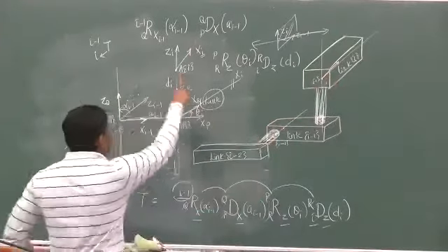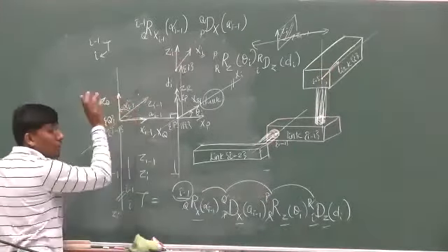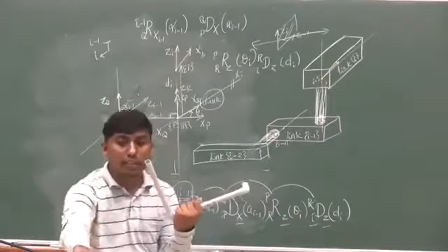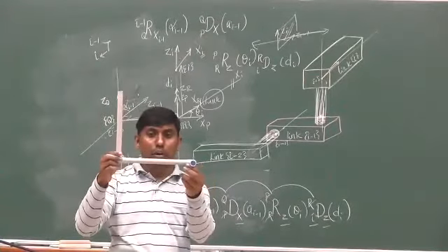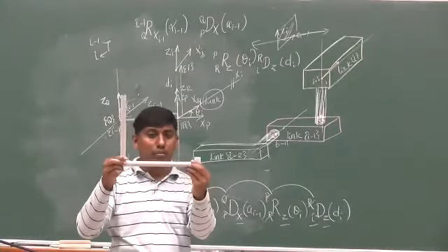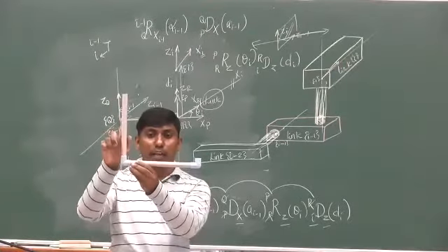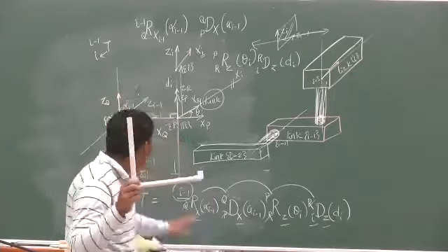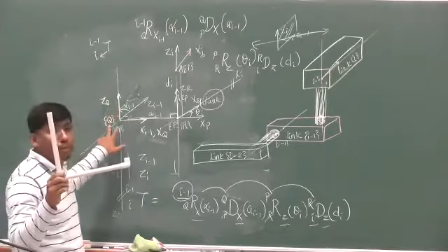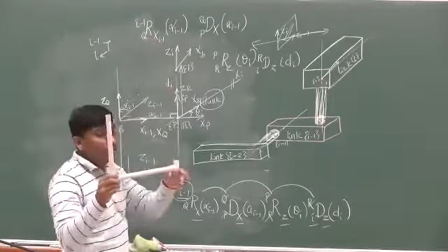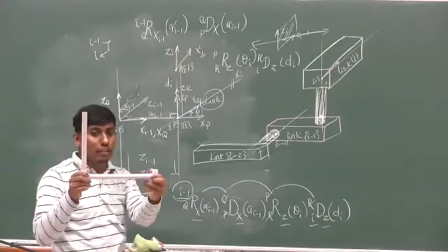With respect to this, you can see that xi is going inside and zi is here, and this is your zi minus 1. The first thing we have done is take this link, which initially was like this, and make it parallel. We first draw the common normal and make it parallel. Now you can see zi and zi minus 1 are parallel. This is the first operation we did, where we obtained zq, the frame q. This is with respect to the x-axis, because we have done it with respect to this axis.